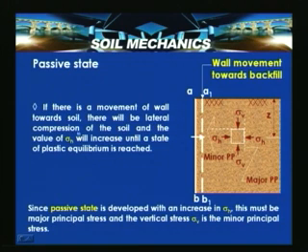So, if there is a movement of the wall towards the soil, there will be lateral compression of the soil and the value of sigma h will increase until a state of plastic equilibrium is reached. Here, if there is a movement of the wall towards the soil, lateral compression of the soil takes place.